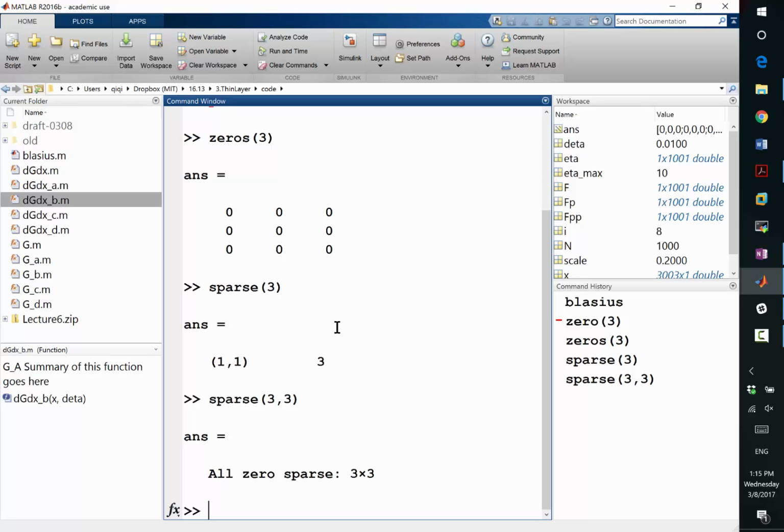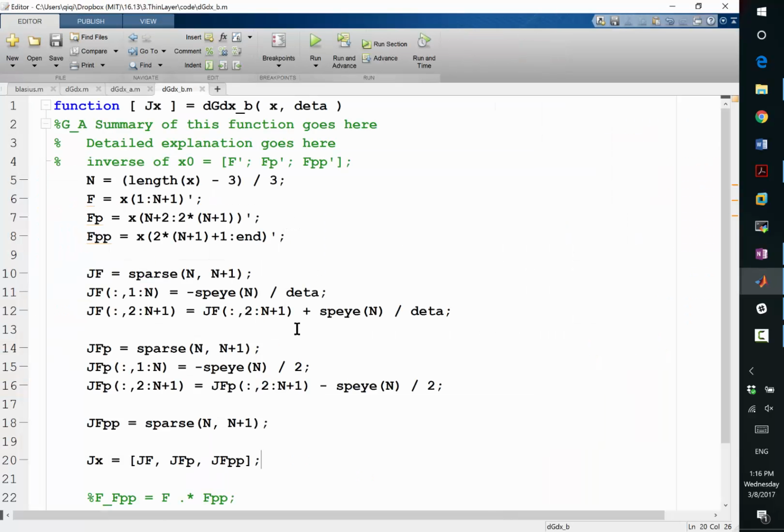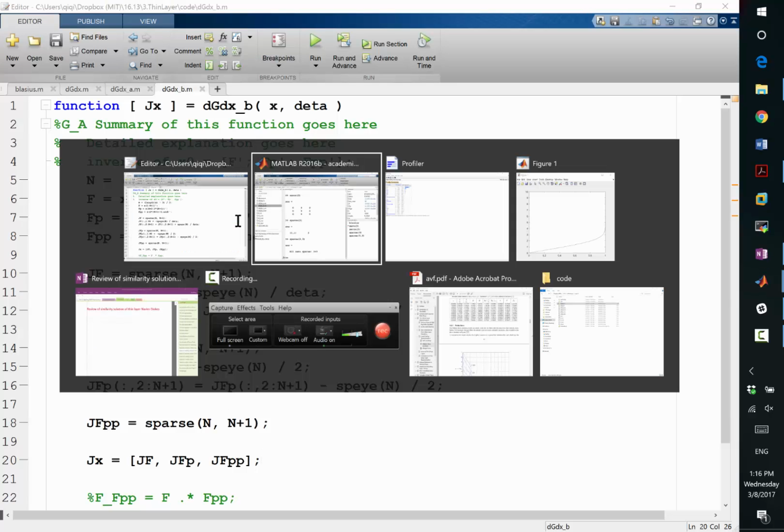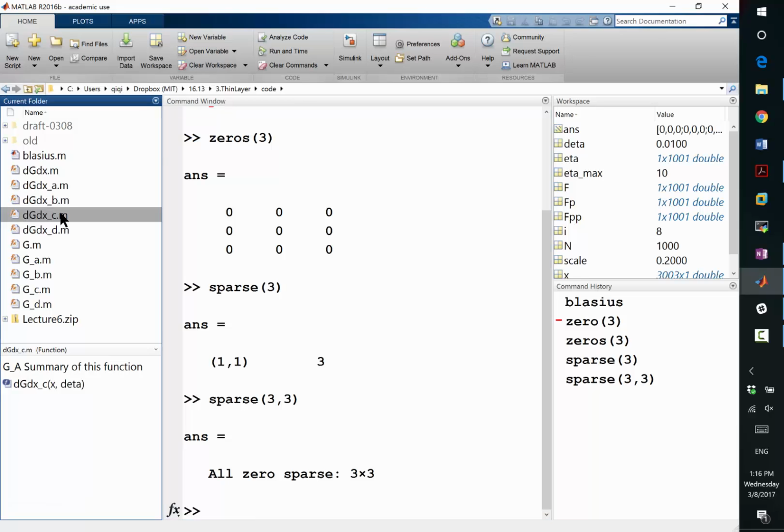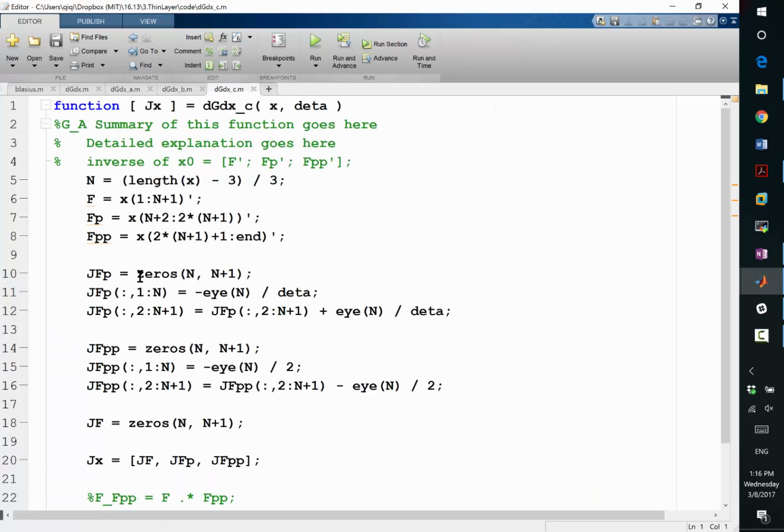How thick is the boundary layer from here to here? If you look up, eta equal to 1 corresponds to about 0.4 times the free-stream velocity. We have completed the modification. Eta 1 is basically how much further from the wall you have to go in order for the velocity of the Blasius profile to equal 40% of the free-stream velocity.